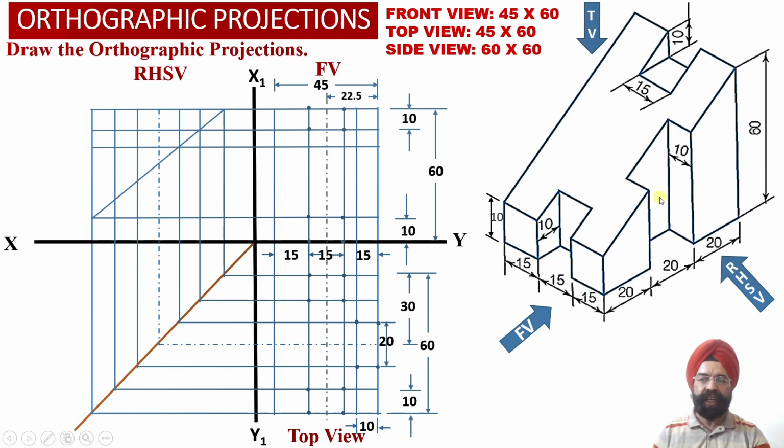This edge is closer to the front face of the solid. Now we draw a horizontal projector line through this edge of this rectangular slot and transfer it using this transfer line into the right hand side view orthographic projections. Now we can check this vertical projector line intersecting with this inclined surface.